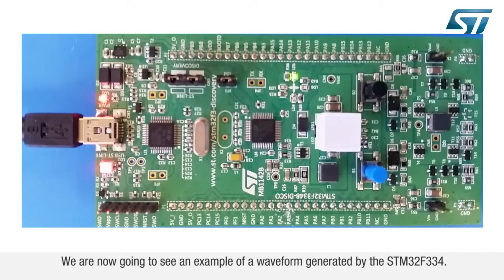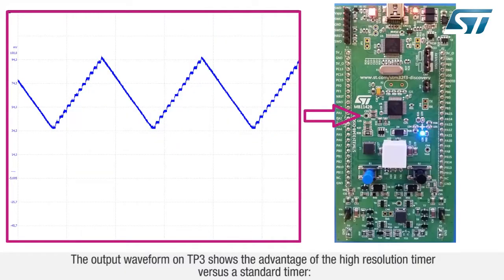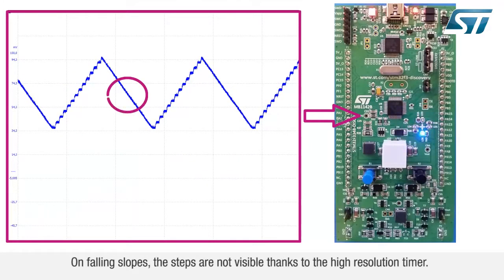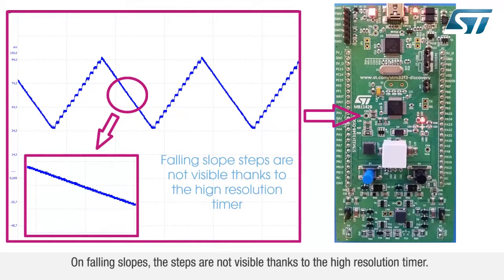We are now going to see an example of a waveform generated by the STM32F334. The output waveform on TP3 shows the advantage of the high-resolution timer versus a standard timer. Rising slope steps of the filtered PWM are visible with a standard resolution timer. On falling slopes, the steps are not visible thanks to the high-resolution timer.